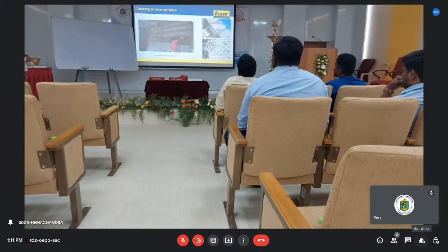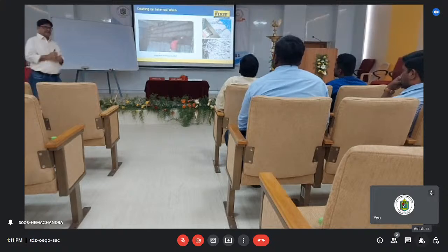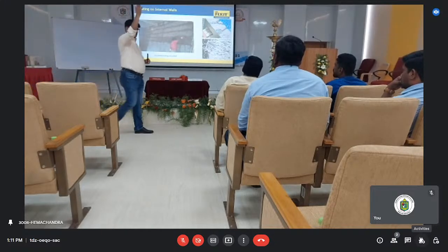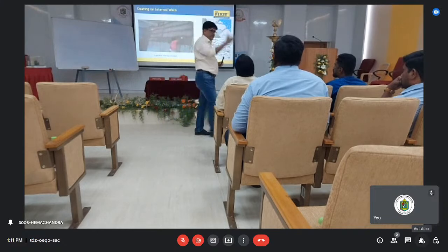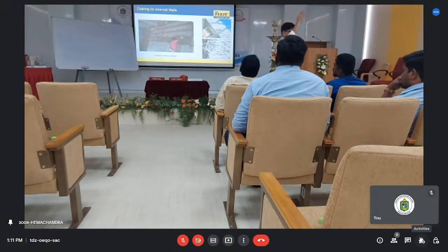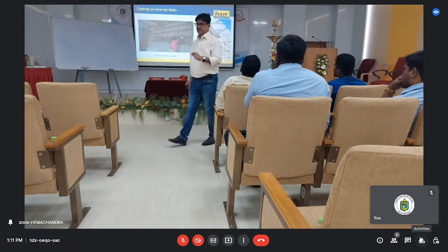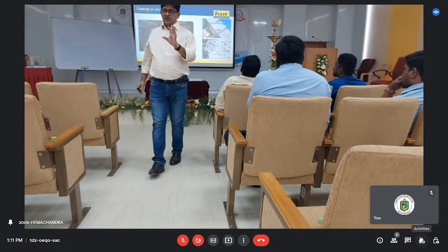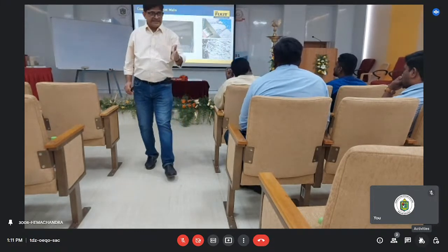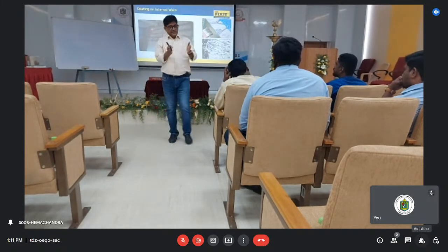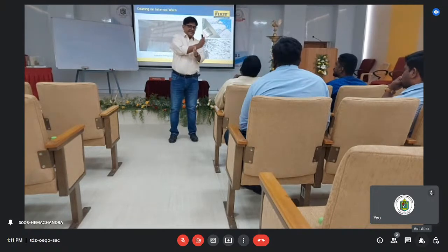After this process, as I told you, filling up is how the crystalline works. After the joints have been done, we have to apply a crystalline as a surface application coating. Now, crystalline is applied as a coating, but crystalline is not a coating. Crystalline penetrates inside. When you apply the crystalline material with a brush, it goes inside and penetrates the concrete.